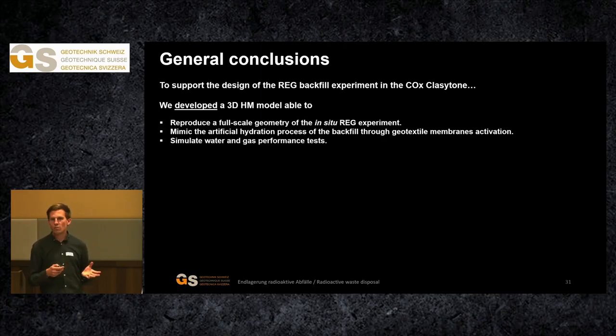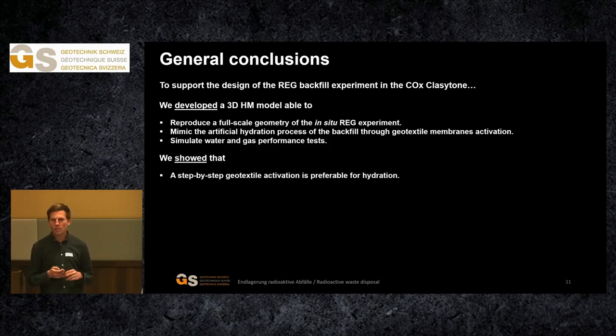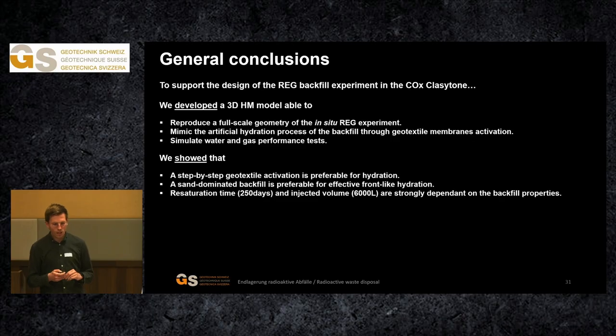And finally, this model was able to simulate the hydraulic performance tests. Using this model, we have demonstrated that the stage-wise activation of the injectors is preferable for the hydration process. We have also shown that the sand-dominated backfill composition is preferable for an optimal resaturation process. We have demonstrated that the resaturation time, computed around 250 days for the reference case, as well as the injected volumes, around 6,000 liters, are strongly dependent on the backfill parameters, basically the permeability, but also